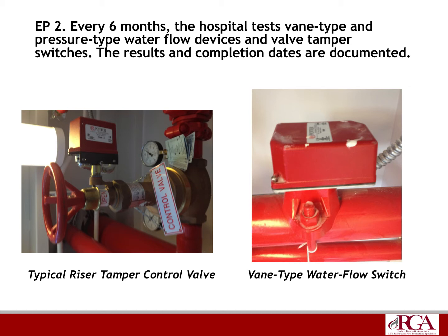So when you get a water flow switch, a typical alarm would be a water flow alarm, third floor, stair A. Now, that's not the origin of the actual water flow or sprinkler that's been activated. That's just simply where the riser resides. That is where the control valve and the water flow switch reside. So if you're responding to this specific alarm, you want to scour the entire floor or zone that it serves, as you don't know the specific origin of the water flowing. You want to look for signs of water flowing and or signs of fire, because if a sprinkler head activates on the third floor, it doesn't tell you the specific area that it's activated. You still have to walk the entire floor or zone that it serves to verify where water is flowing.